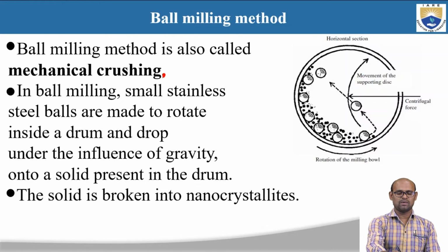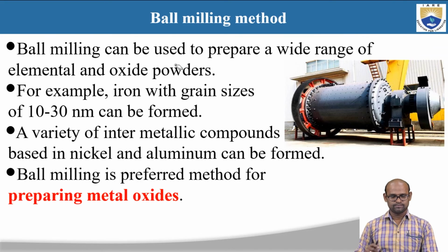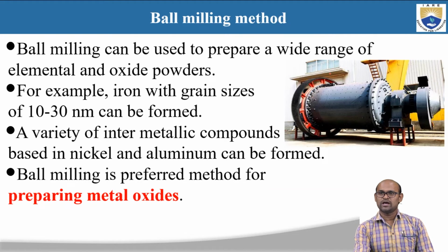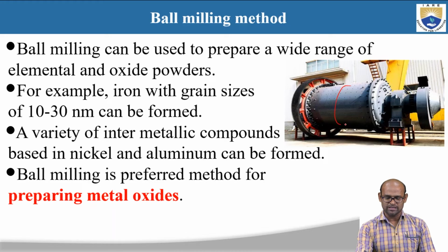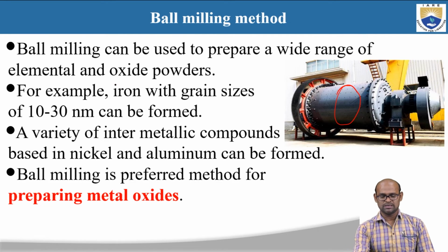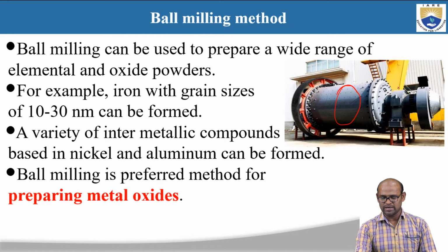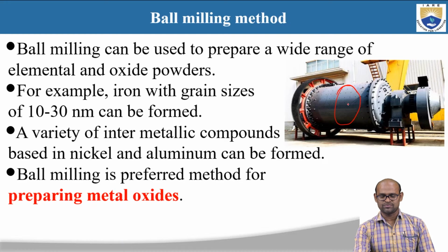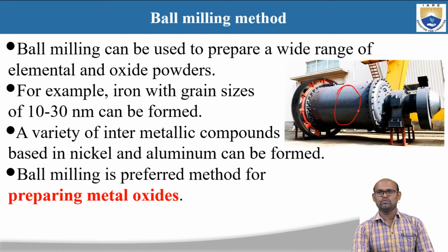So that is why this ball milling method is also called mechanical crushing. This is the experimental setup. We can see it clearly, but what is happening inside is what we have seen here. So this is the drum. This drum is rotating and there are stainless steel balls inside this drum,